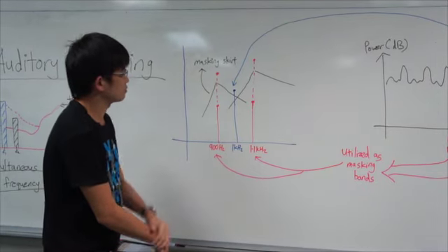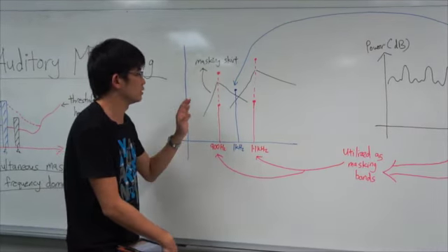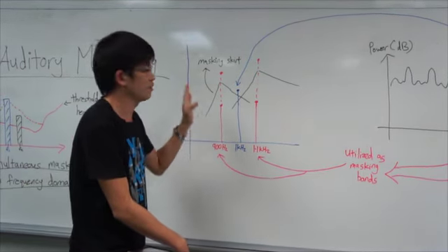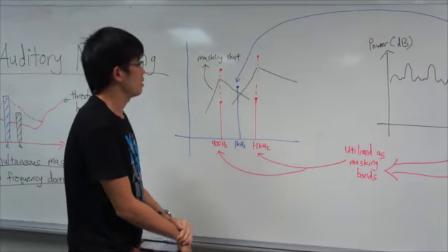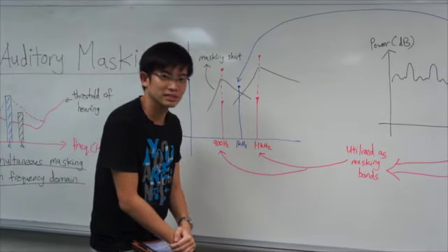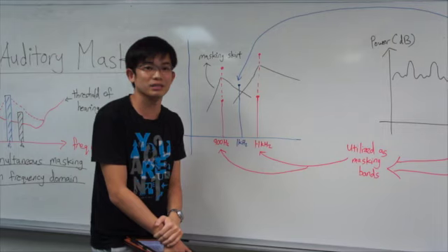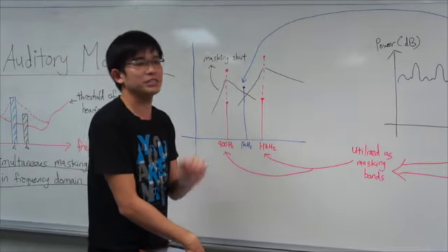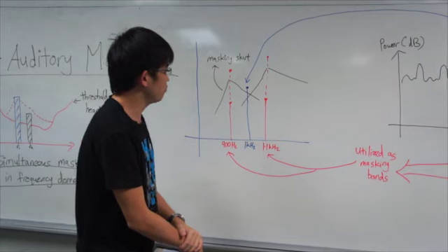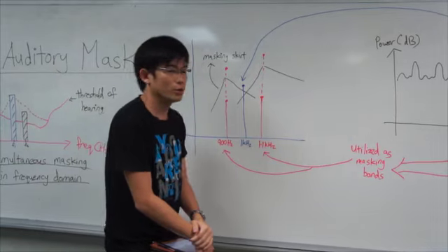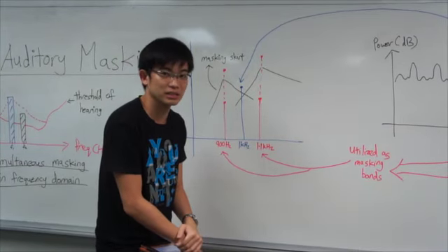So based on this concept, we decided to choose the lower adjacent signals to be a masker to mask out the 1 kHz tones. But after going through a certain amount of testing, we realized that this masker is not sufficient to mask out the signals due to the fluctuations of the signals. Therefore, we decided to use the higher adjacent signal, which is 1.1 kHz, to complement the 900 Hz masker with a significant gain increase.